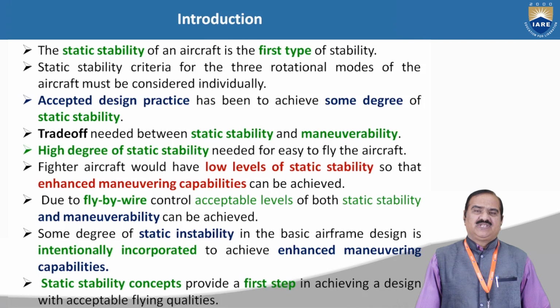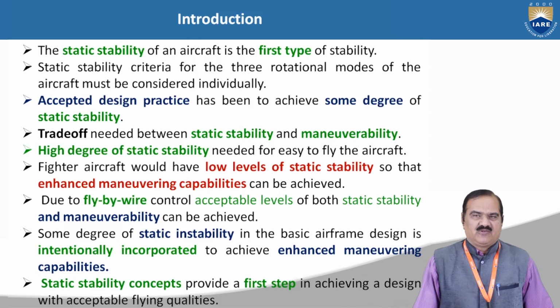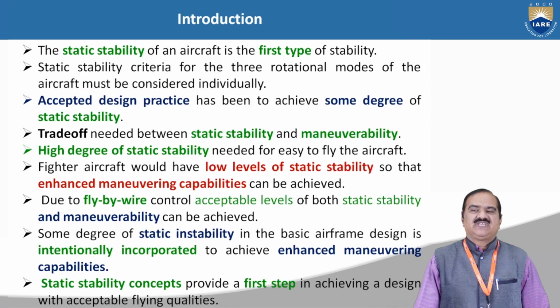There are two things, stability and maneuverability, and we have to trade off between static stability and maneuverability as per the requirement of the aircraft. A high degree of static stability is needed for an easy to fly aircraft, to have very smooth and simple flying.